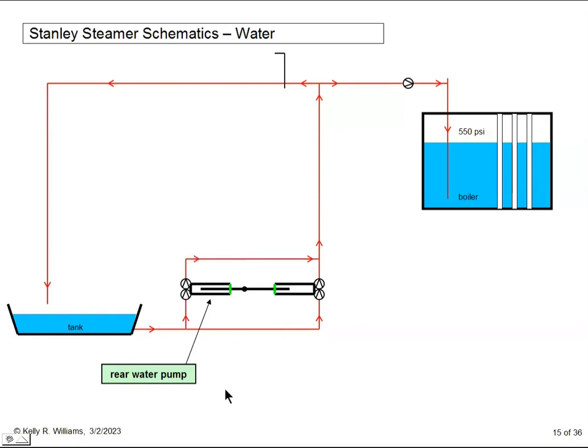We'll add a suction line for this pump, the same two check valves for the same reasons, and connect its output to the delivery line. But if you recall, the front pump by itself is a pretty good match for water consumption on moderate terrain. If both pumps delivered all the time, we'd have to twiddle the main bypass more often, switching between feeding too much water and not feeding any at all.